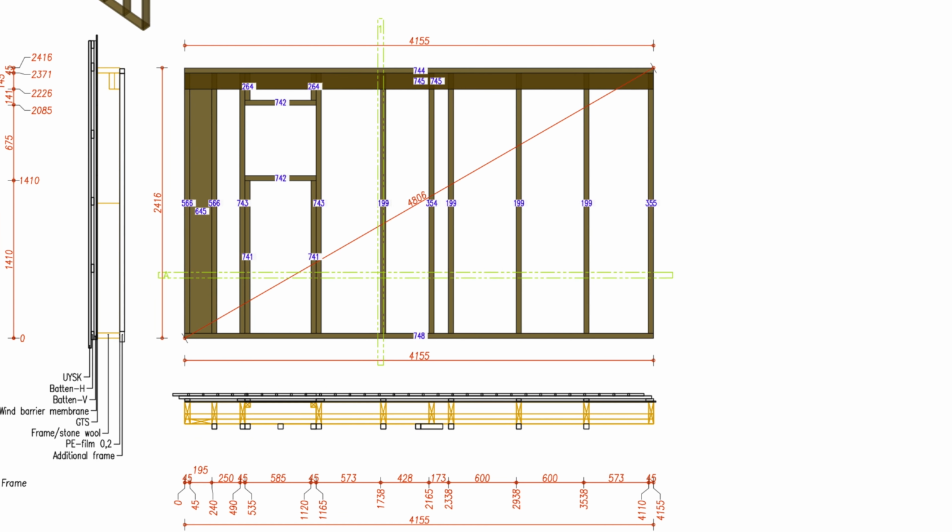Now, looking closely at the horizontal section, we can see that this stud is adjacent to the first stud, but rotated to a perpendicular position. The spacing of 195 millimeters shows both the width of the stud and the fact that the following, third stud, also numbered 566, is opposite the cross stud, and the distance from the starting point is 240 millimeters. The fourth stud, numbered 743, is located 490 millimeters from the starting point.